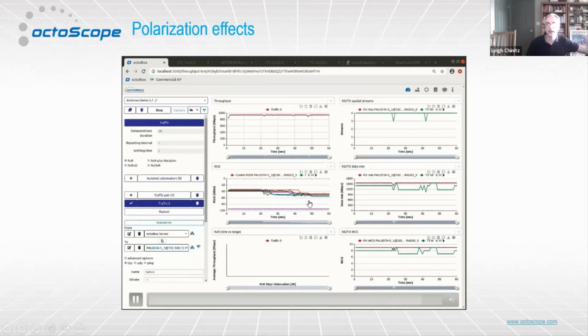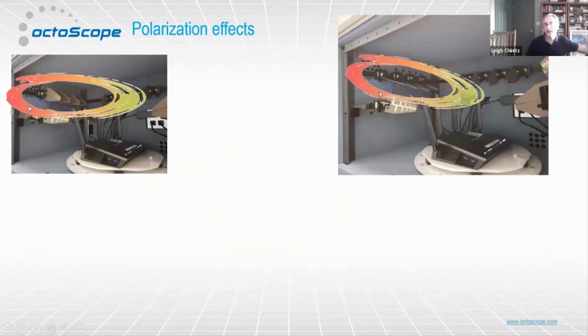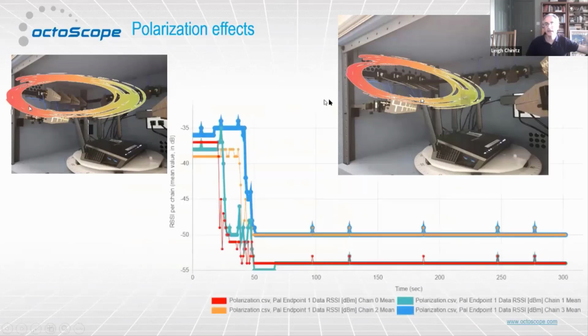It's a little hard to see at this scale, but this is the test I did. If you look at the device under test, you can see that the antennas are clear, sort of dipole-like antennas. You can see their polarization. And if you look at our antennas, it's this set of 4 up here. You can see I initially had them aligned with the device under test. And then what I was doing was individually turning each one so it would be cross-polarized like that. If you zoom in on that data, you can see the effect. It's actually a fairly significant effect. We're looking at about 15 dB from cross-polarizing the antennas. So you can see a fairly noticeable drop in the received signal level.